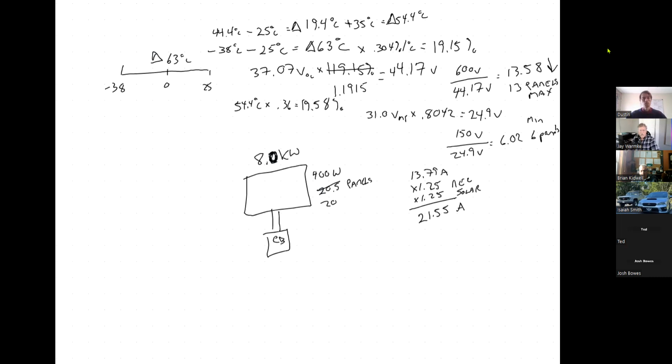But it might be 30, it might be 10 gauge wire. If it is 10 gauge wire, we're fine. If it's 12 gauge wire, we're still fine because the maximum for that is going to be 25 amps, if you read it in column 1 in the table that's on page 104.